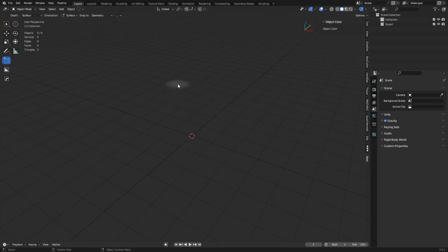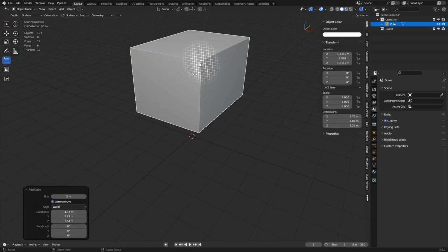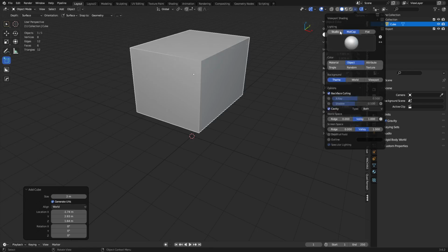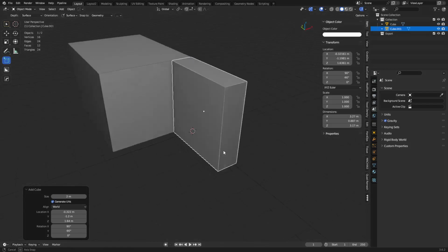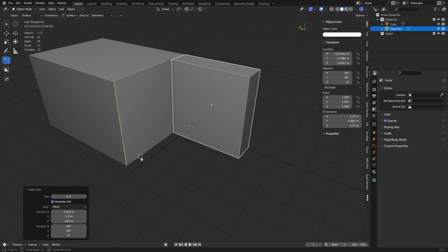But if we were to create a cube real quick, we can hold Control. You see the little circle pop up in there? It's kind of hard to see it, but let me take this and change this real quick. Something like that. There you go. Okay, so you see the little circle, right? It's snapping to that corner. We hold Control the whole time. We can snap to this edge down here at the bottom, and we can let go and click. Bam. There you go.